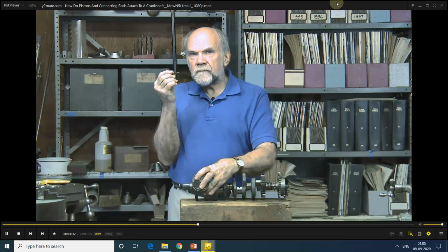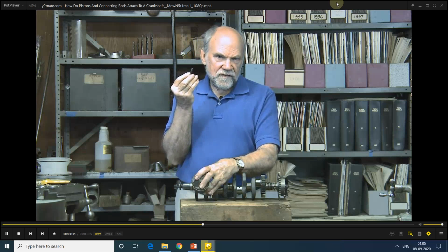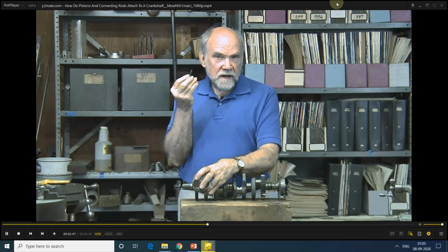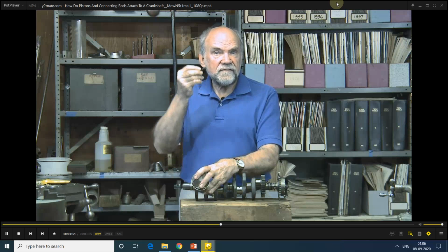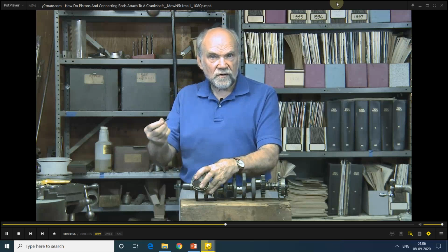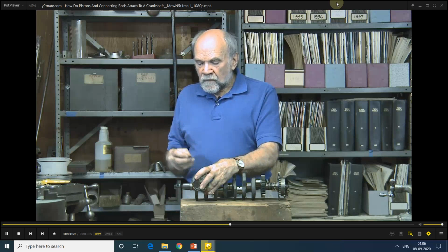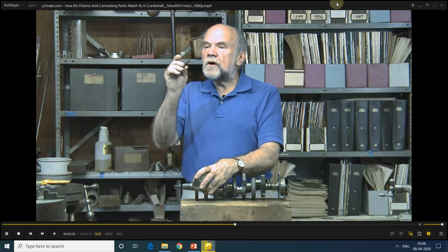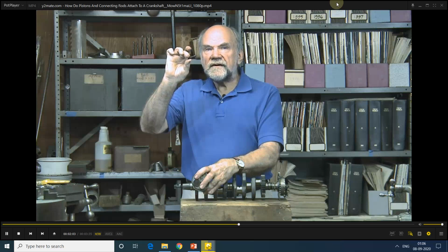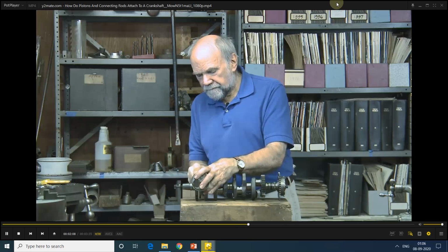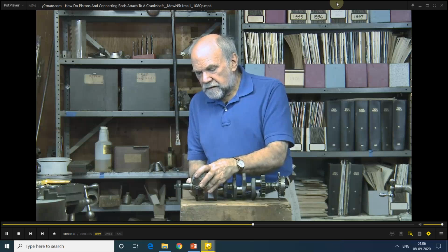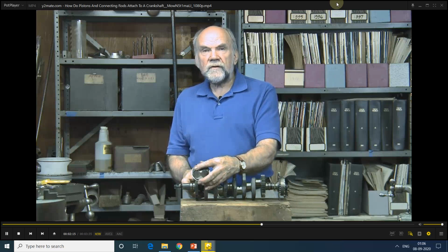These bolts are responsible for making sure that the piston obeys orders at top dead center. It doesn't keep going and smash all the valves flat. Instead, it is obediently dragged by the crankshaft down on either its suction or its power stroke. So these bolts have to be remarkably strong. The metallurgy in connecting rod bolts is usually of the best. Once the bolts are in place and they've been torqued to the correct preload,